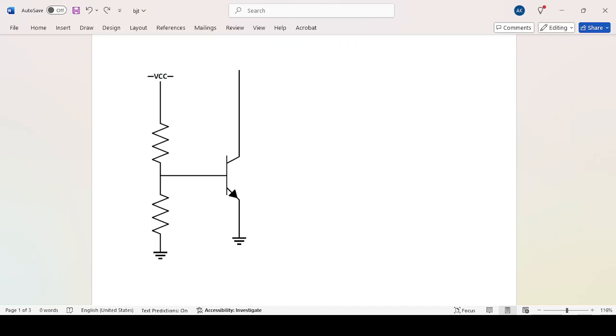And when we tape out a chip and it comes back, it wouldn't work, or it would work based on lots of variation, like temperature, noise, and other stuff. So it is very important to design a very robust current source in both CMOS and bipolar, but maybe in bipolar more accuracy is needed.